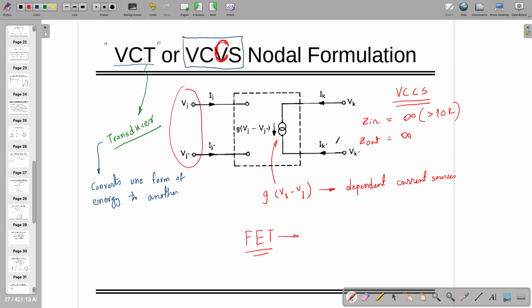Have you heard about this ever? No or yes? How many have heard about this? Can you raise your hand? Like MOSFET, right? Yeah, like MOSFET, okay. JFET, yes. So such a FET is here. This is a field effect transistor because the input is voltage. It's controlled by field. BJT is the one which is controlled by current, so it's a current controlled current source, but MOSFET is a voltage controlled current source, where the input is field.